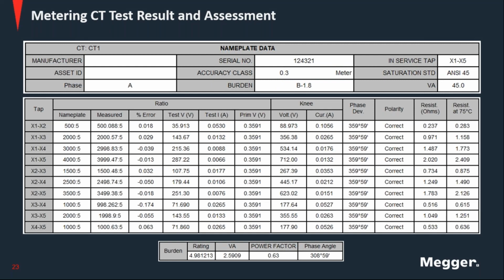Each instrument transformer will have its own classification, and depending on what standard it was built to, you also need to evaluate against that standard. And that was my reference to the transient transformer. So if you have a transient transformer, you need to select IEC for the assessment. This is what determines how this information is going to be used for the calculations of the assessment.